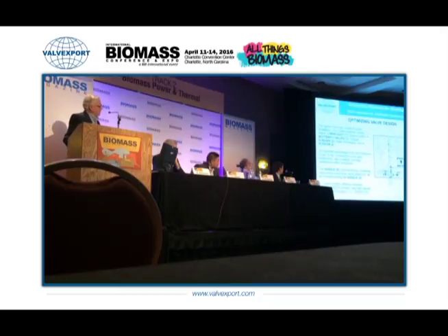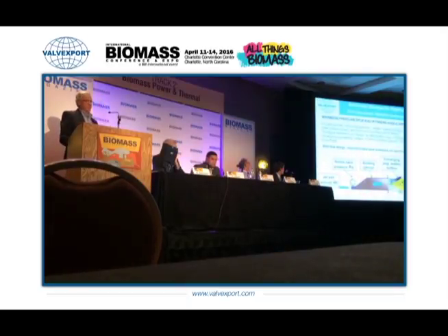The current design takes pressures from ducts and puts the air through this passage that creates not only high pressure losses, but also creates turbulence before the jet, and therefore you can require as much as 2 times the pressure with this type of valve than you require with this type of system. And what we are showing at booth 501 is a small version of this type of device.